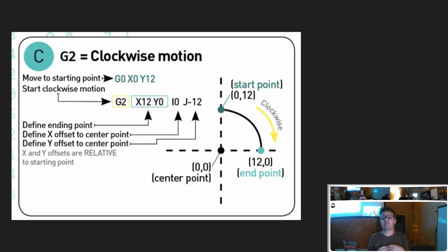This is where you can understand the flavors of how G-code got a little buck wild down the line. They started adding all of these commands for describing arcs and different types of curves and Bezier curves and different kinds of special motion where you could get very complicated motions on the machine in a single line of G-code. Those were added to old machines because if you fed them a 1 gigabyte G-code file with every single little position for my curve, it would crash the memory on the machine. So they made fancy commands to overcome that, and all the machines support different versions of fancy commands.